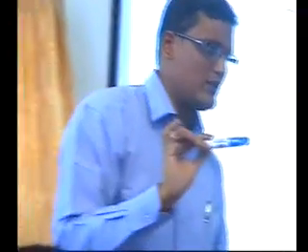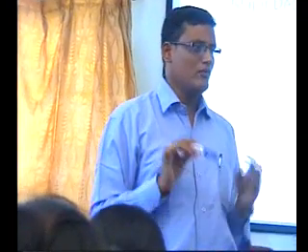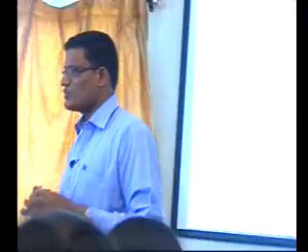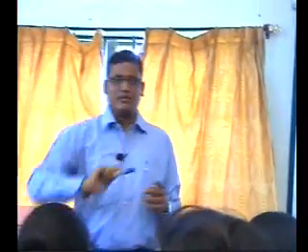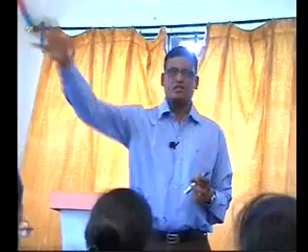Similarly, every kind of circuit, a sequential circuit, may be in need of a clock. Mostly it is in need of a clock signal. To every corner of this particular circuit, if you want to apply the clock, there are many types. One popular one is the H-tree. Like the English alphabet H, you can organize your clock to different branches of the circuit.